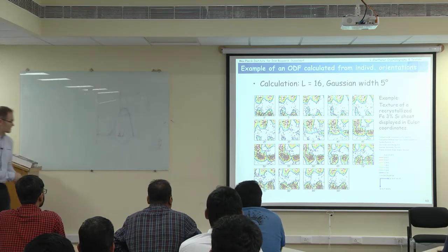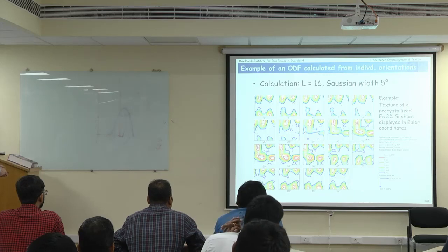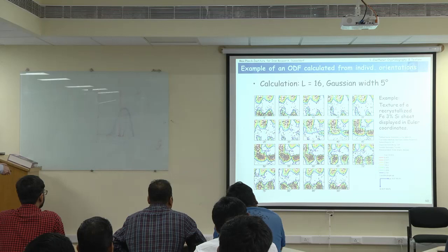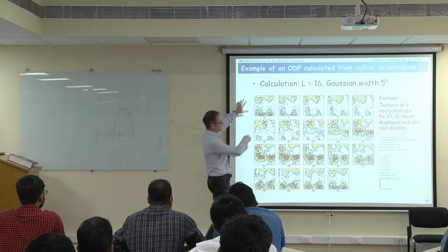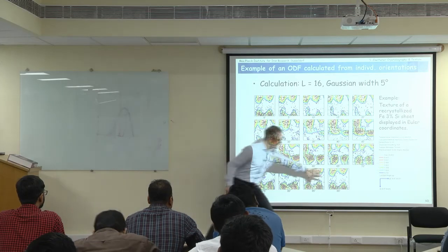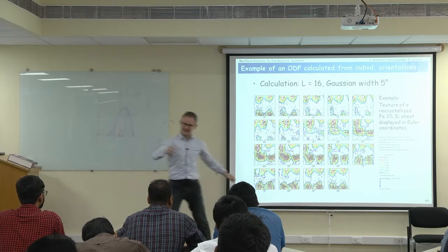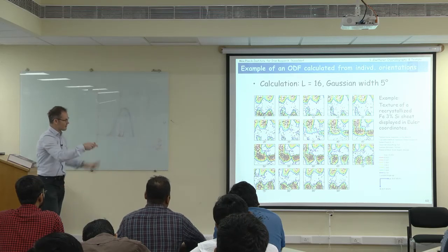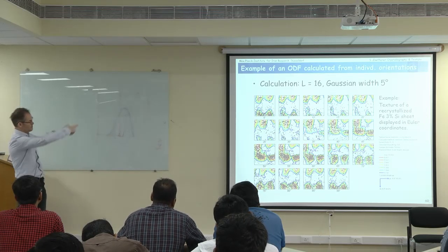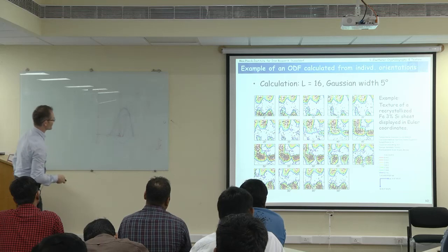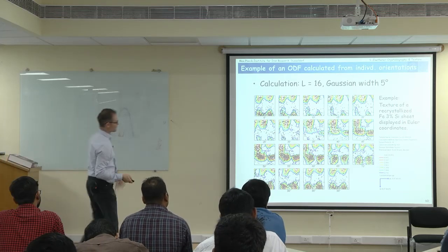And here you see something interesting, actually. You see there are many spots here, one peak, and here's a similar peak, but there are many spots in one and few spots in the other. The reason for that is that I have limited my plotting to only up to 90 degrees, so I'm missing some of the symmetrically equivalent points. That's why we are seeing a little bit of difference in the spot densities, although in principle it's all there. I would have to plot all the way to 180 degrees to see the full density and correct correspondence of spots. But you see how it fits together.